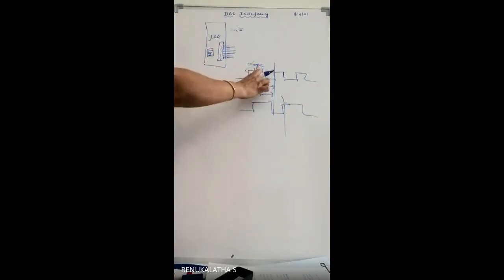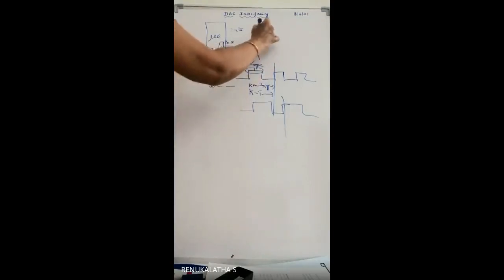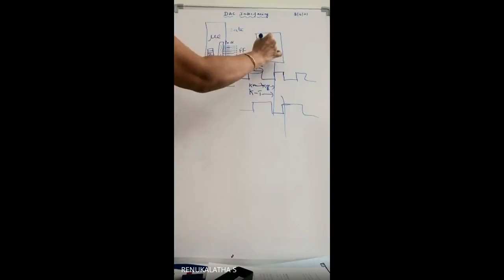So when the on and off periods are the same, we call it a square wave, with equal delay intervals. Now let us see. Logic 1 has to be passed, so place 1, 1, 1, 1 here. That means FF. 8 pins you can take, as usual from P0.16 to P0.23. On all the 8 pins you pass 1, 1, 1, and this will go to another circuit which we call a DAC.